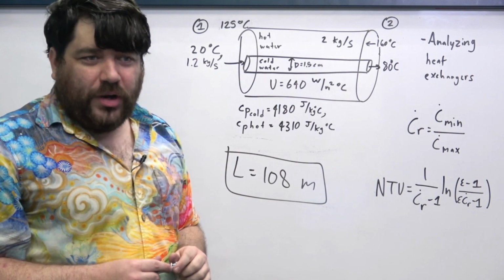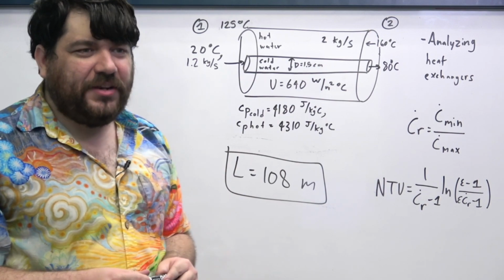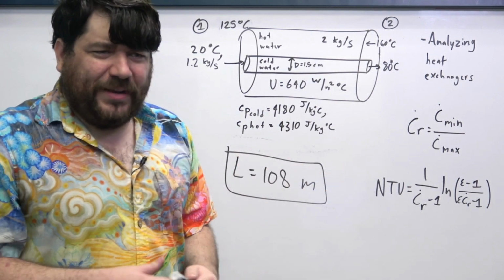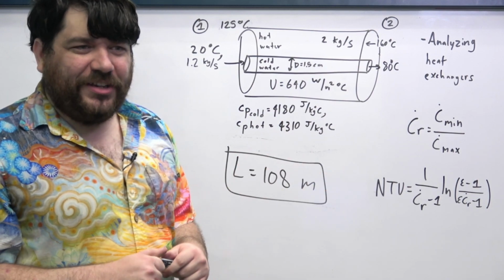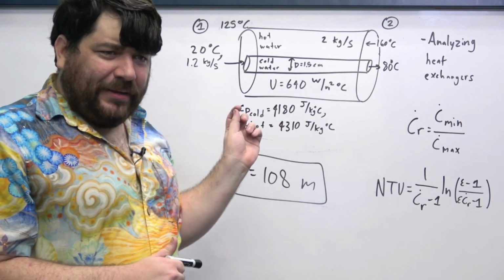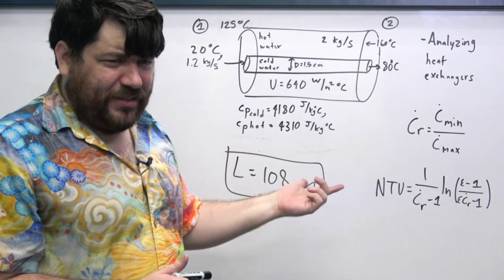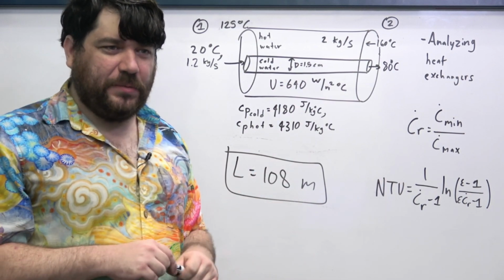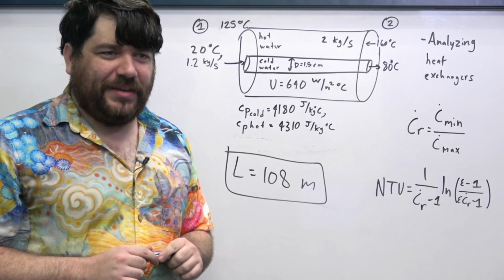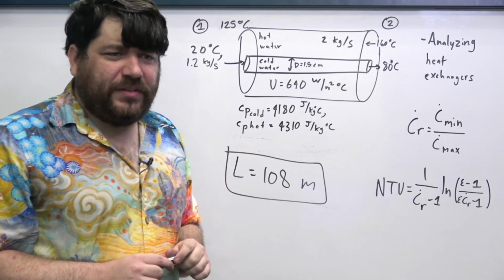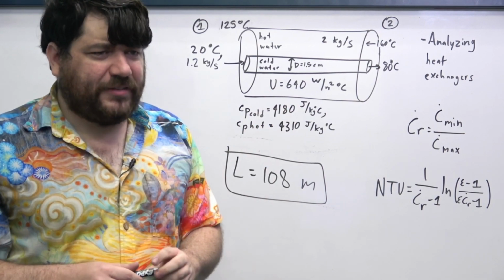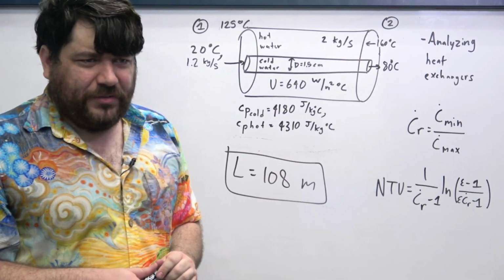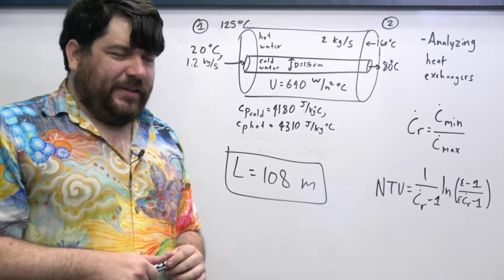That correction factor is 1 whenever we have a counterflow heat exchanger, but if this was a crossflow heat exchanger, the workflow is to basically pretend like it's a counterflow heat exchanger and then just multiply U times AS times delta TLM with a correction factor F to get the actual heat transfer rate Q. Everything else follows in the exact same way. And so this tells us everything that we need to know, or at least most of the practical paths that we can take in order to calculate the properties of heat exchangers, right?